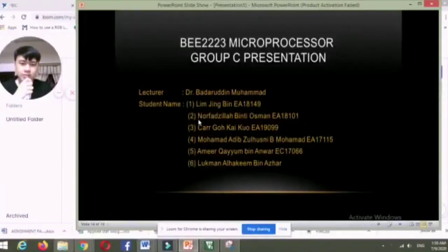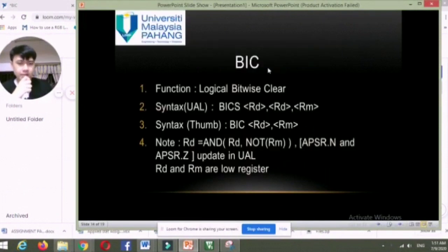Good evening, everyone. My name is Lim Jingbing, and today I will start my Group C presentation. I will talk about the BIC instruction, which is part of the logical instruction set of ARM assembly language. Its function is logical bitwise clear, and its syntax in UAL, which is Unified Assembler Language, is BICS, Rd, Rn, Rm.